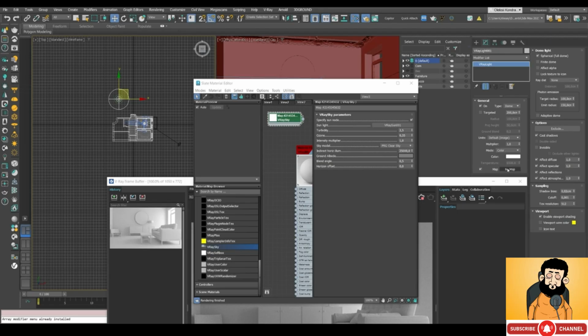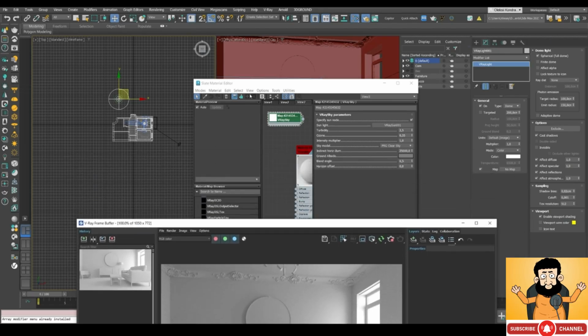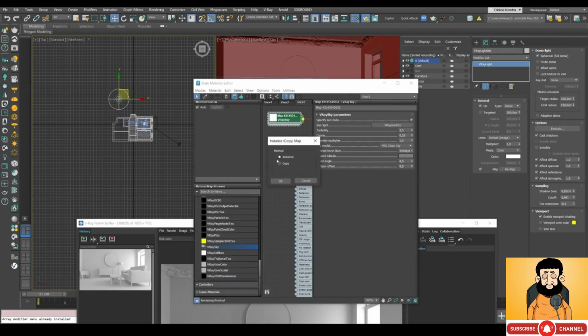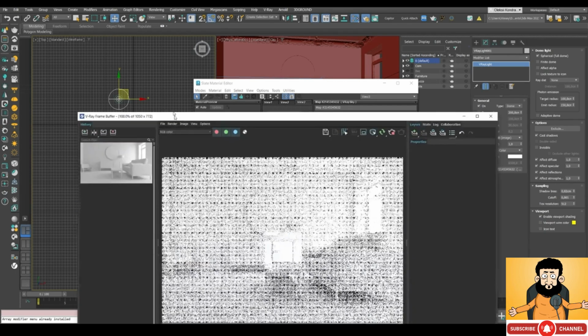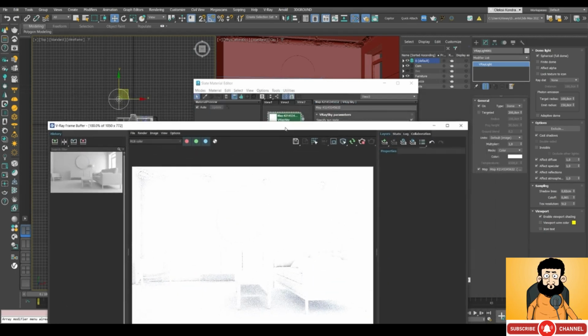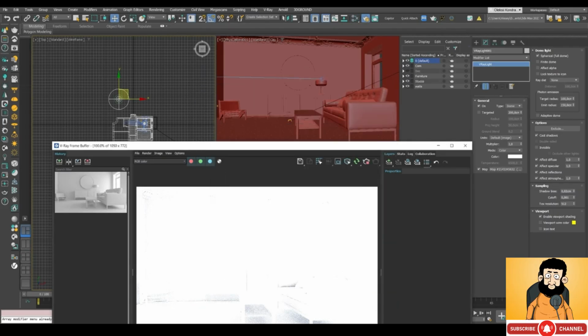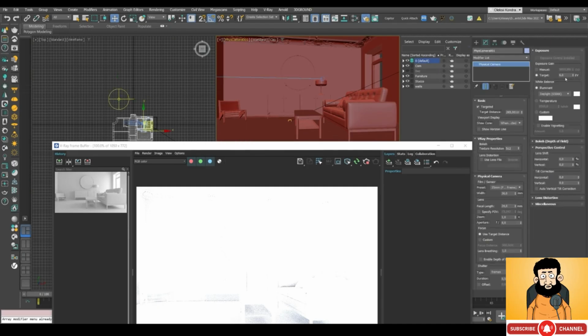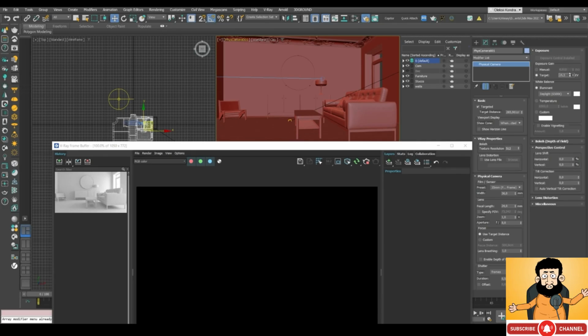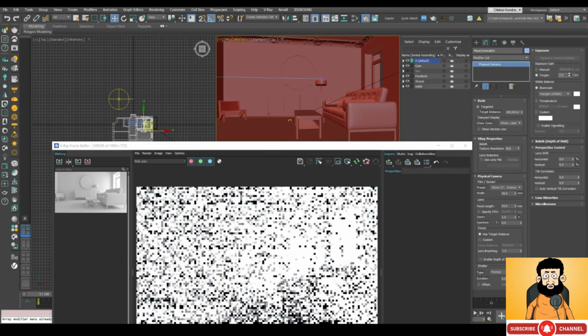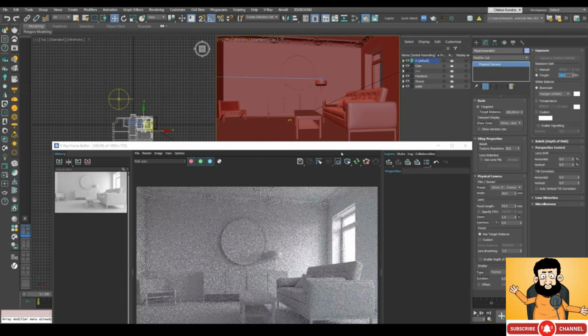So we can add it as a texture map by clicking this No Map button. We take V-Ray Dome and drag it to the No Map slot as instance. Make sure to make it instance so that when you change sky parameters in Material Editor, they change in the dome settings as well. See, the light has changed completely. That's because we now have V-Ray Sky. So now we need to adjust the exposure and the camera settings. We're raising it. Let's make it 10 for now.